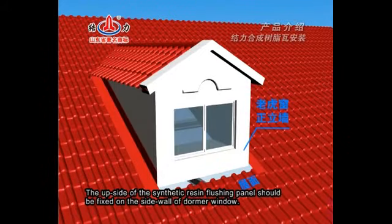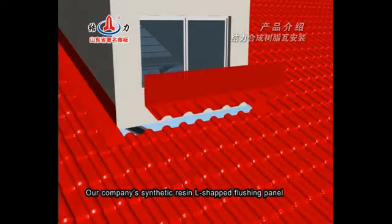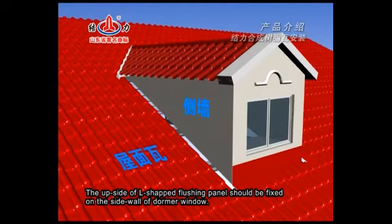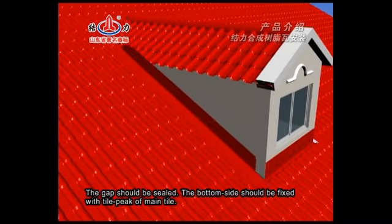Our company's matched synthetic resin flushing panel can be used for the waterproof process. The upside of the synthetic resin flushing panel should be fixed on the side wall of the dormer window. The gap should be sealed. The bottom side of the flushing panel should be fixed with main tile. Our company's synthetic resin L-shape flushing panel can be used on the connection between the profile wall of the dormer window and roofing. The upside of the L-shape flushing panel should be fixed on the side wall of the dormer window. The gap should be sealed. The bottom side should be fixed with the tile peak of main tile.